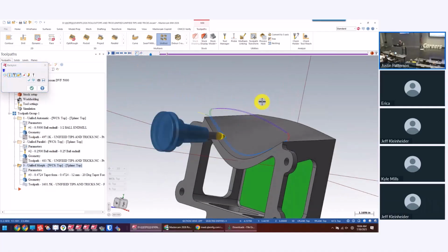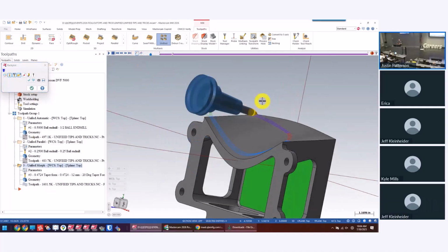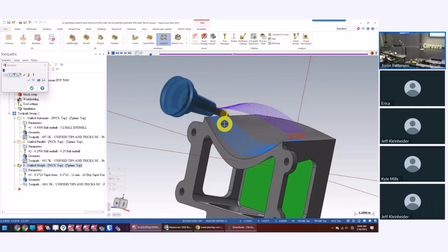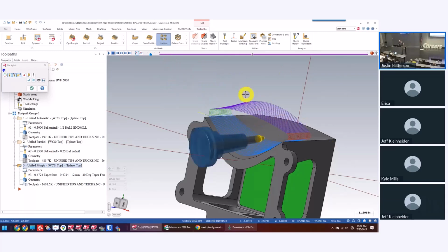You're almost doing like a helix bore of some sort. It's just nice, smooth motion for your machine. If you want to make those corner radiuses a lot more, go ahead and do that. But one problem, let's say this is titanium, and I'm cutting this, you know, I don't know the titanium feeds and speeds for this. I'm not going to put you on the spot this time, Christian, I promise. But I don't want to run real slow through here.